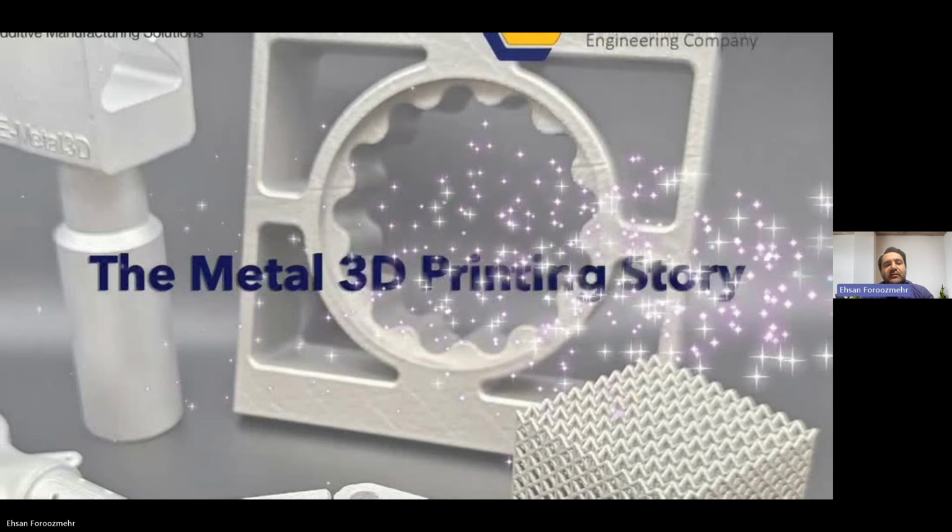The next software is where you define process parameters. What laser power should be used? What scanning speed should be used? What overlap between the layers is used in order to have the best properties, and many more parameters. Everything is predefined in this software. As you can see in this video, there are some very fine lines that are the track of the laser for each part. By moving the scroll up and down, we can see the design of each layer as it was in the previous software.